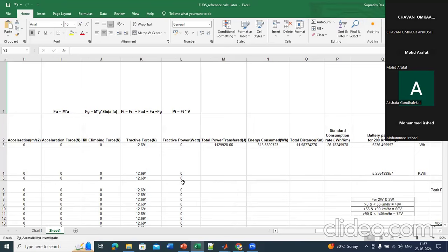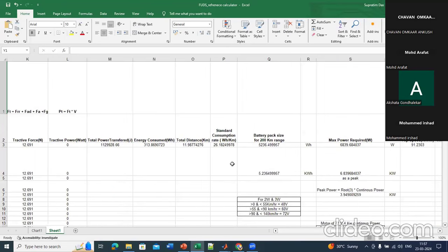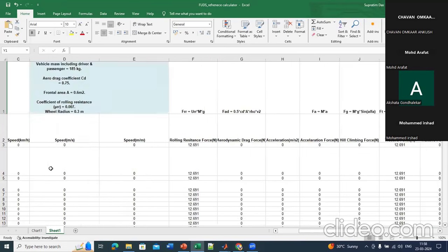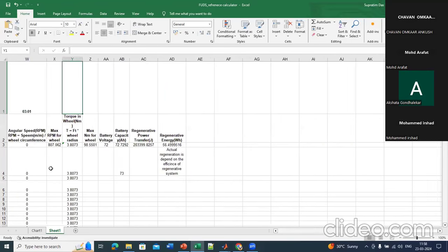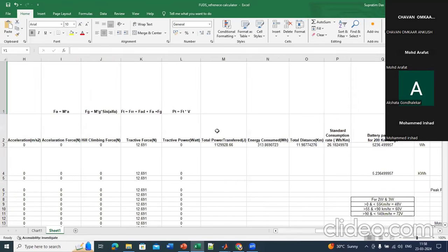In the real case, what we generally do, as you have seen here with this powertrain component selection, is repeat the same process, not for only a single drive cycle, but for multiple different drive cycles based on the vehicle type. So suppose for the 4-wheeler, I am doing it for FUDS, WLTP, MIDS, IDC. Multiple drive cycles, I am calculating the same parameters.